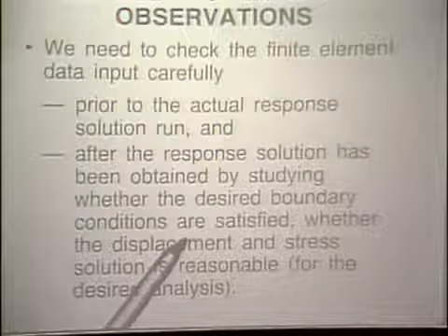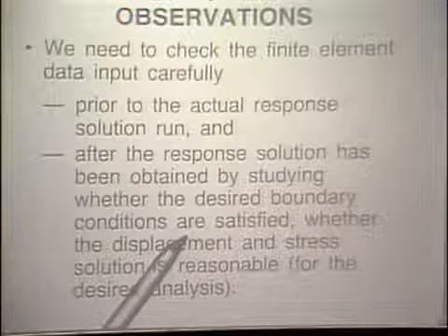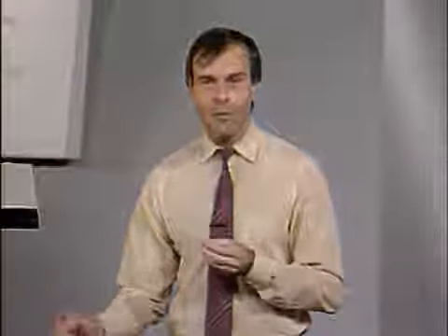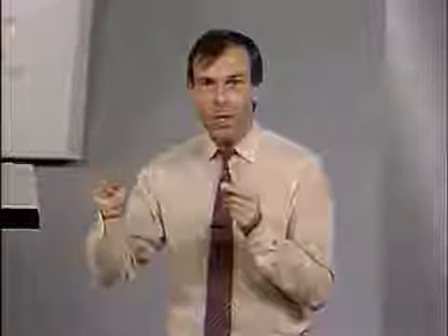Remember, in our analysis, we did this as well, and we found by looking at the boundary conditions, the way they were represented in the actual solution, that we had actually made an error. In other words, we looked at the deformed mesh, and the boundary conditions on the deformed mesh in our first analysis showed that we had fixed the boundary at the bottom of the mesh, which was an error. So it is very important to go through this step, to look very closely whether the boundary conditions are actually satisfied on the mesh that you have been using in the right way.